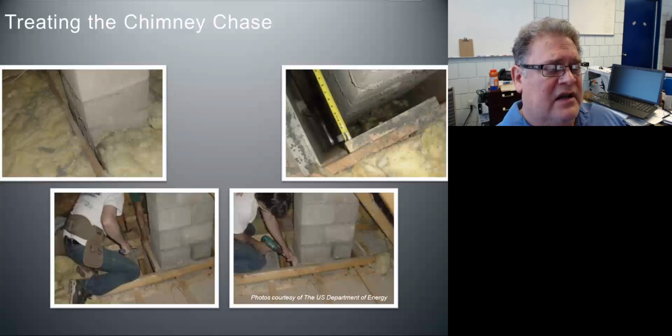So how do we do it safely? First of all, we're dealing with a block chimney, what we call a masonry chimney. And we want to remove the insulation, move it back temporarily, so that we can then come in, look at the top right slide here, or fixture on the slide. We want to make sure that we have clearance to combustibles. We need a minimum of 2 inches around a masonry chimney. Okay, I would recommend going to 3, but a minimum of 2.